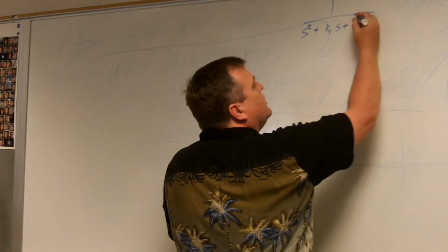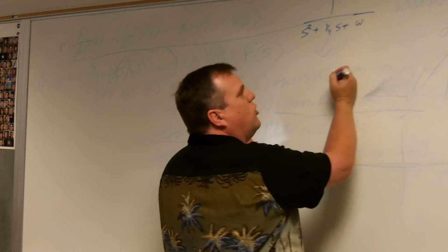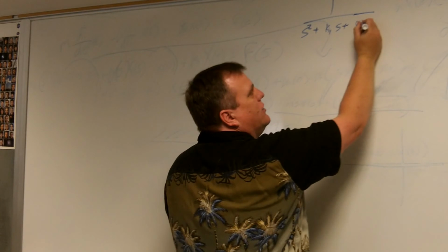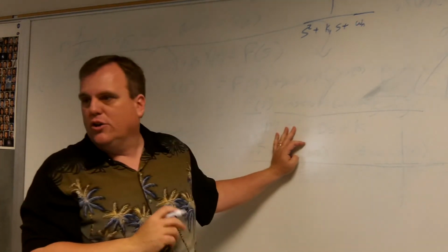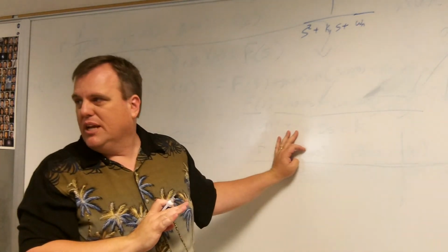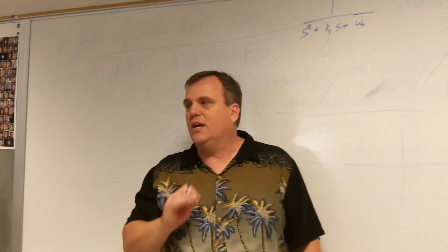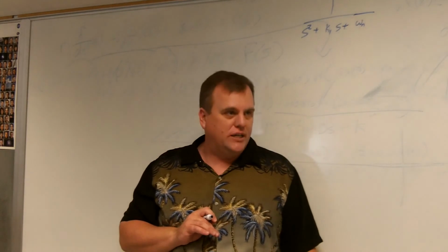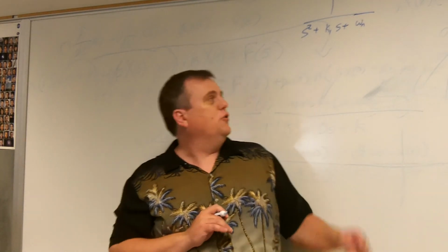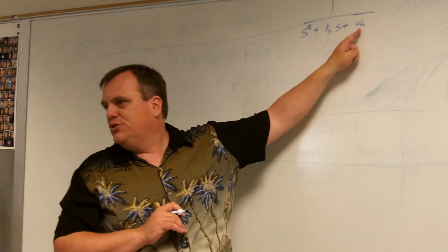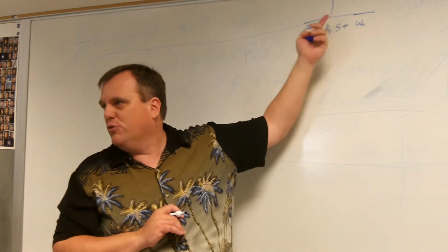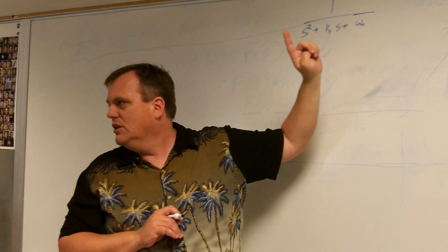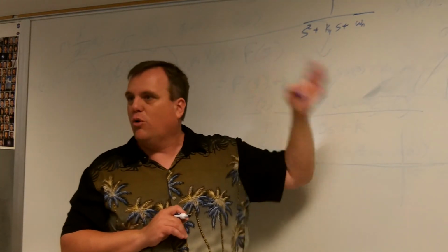So this is either going to be called by people, they either just call it omega, or they call it omega 0, or they call it omega n. It all basically will mean the same thing. I tend not to like omega by itself, because we also use omega for the frequency that you're driving it at. So if you pick omega here, yes, you save yourself one letter, but it's confusing later on when you ask, what is the omega of S? Now you've got omega in 2 places. So I would suggest you either use 0 or n.